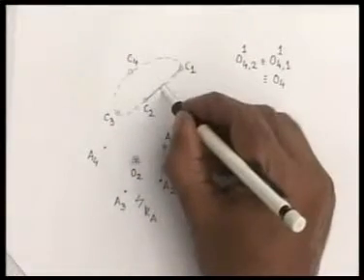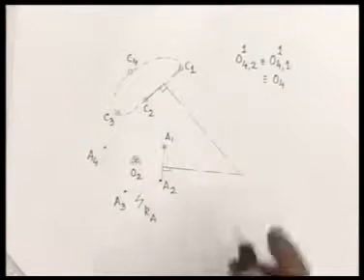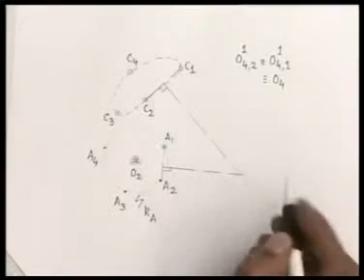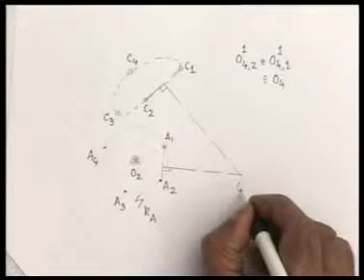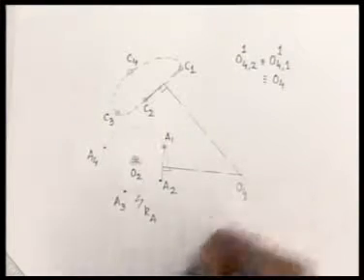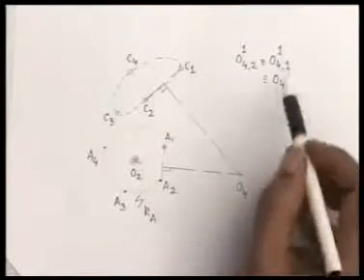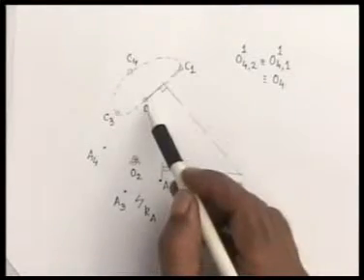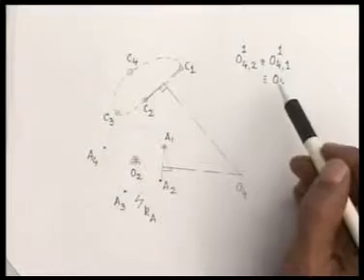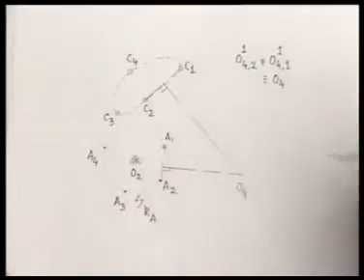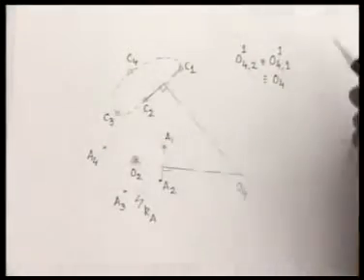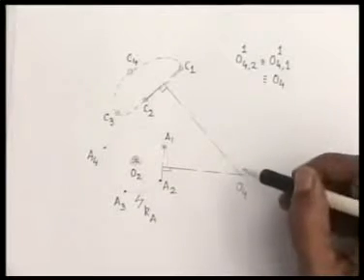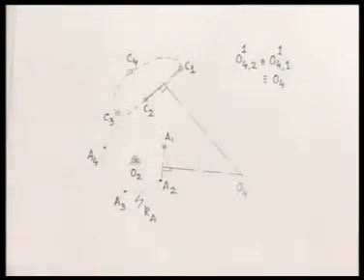This is the perpendicular bisector of C1, C2. These 2 straight lines meet at this point, and I choose my O4 at this location, which is the same as O411. This will ensure that if the second position is inverted on the first position holding link number 3, that is the coupler, fixed, then O421 will also be here.